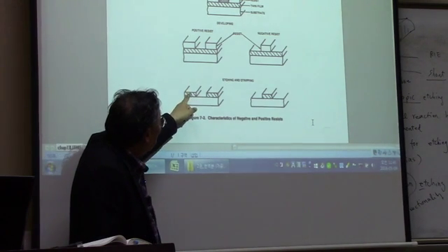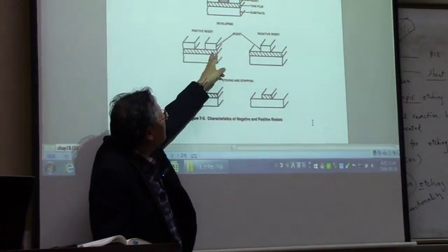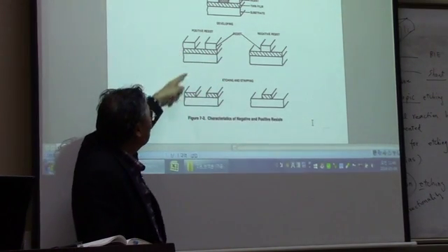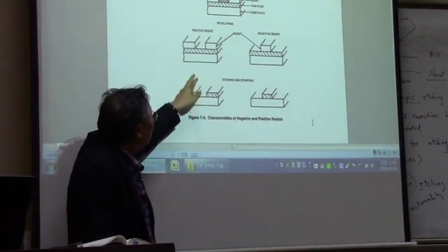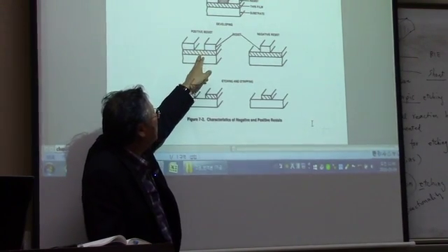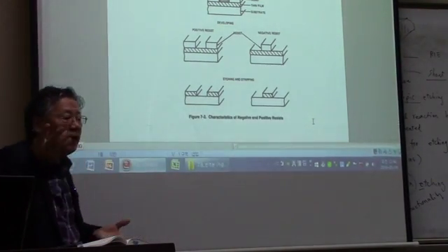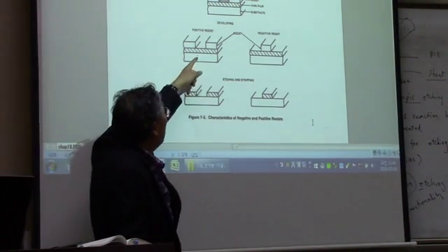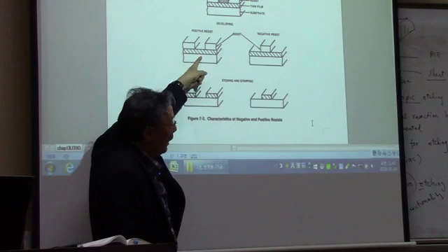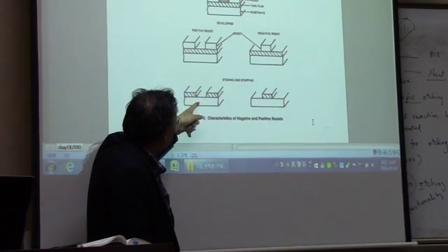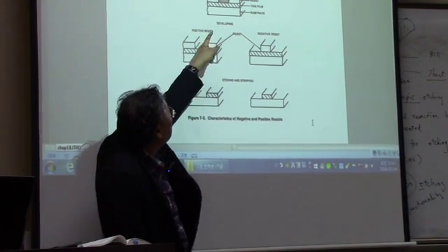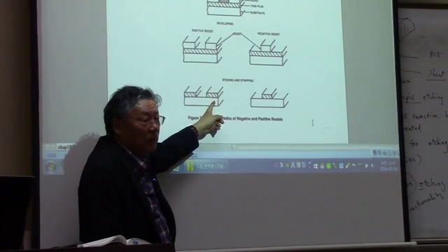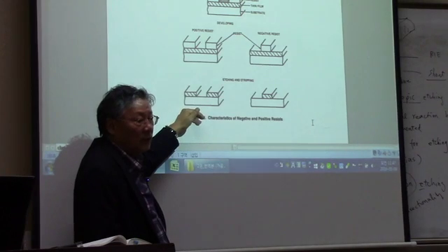Okay, then the thin films, which has been covered by the photoresist like this, only the part exposed to the etch gas in a dry etching or wet etching system, whatever, that is going to be etched so that the pattern of the mask is going to be realized on the thin film, which has been deposited on the silicon.